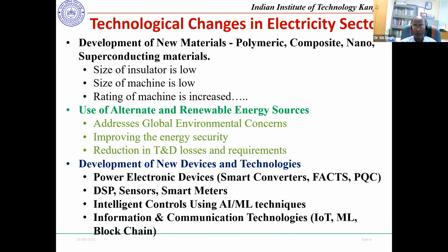How come? The technology is the same. The induction machine principle has not changed, but we have changed the cooling facility. We have changed the insulation materials, so that many technologies are given so that we can increase the voltage level of the terminal. Because for power, as you know, we have to minimize the current for loss minimization, I squared R. For making I less, voltage must be increased. The terminal voltage of the alternators has also increased.